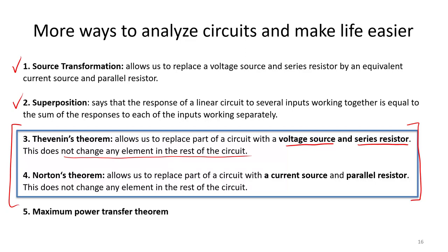Similarly, Norton's theorem allows us to replace part of a circuit with a current source and a parallel resistor. Once again, we are just replacing a part of the circuit that we don't like, so the rest of the circuit that we don't replace remains unchanged. And next time, we will look at maximum power transfer, and we will see that Thevenin's theorem is extremely useful when we apply maximum power transfer.